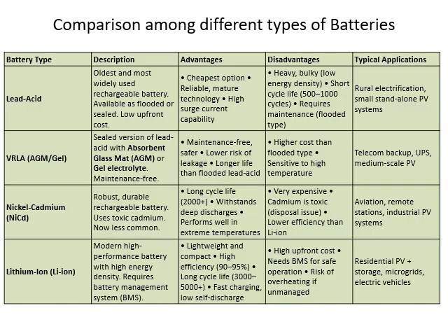Now we will talk about the different categories of these batteries, right? We are going to compare these four types. So we will first look into where we are going to apply this, right? Based on the application, we should try to see, then we will compare between them. So we can see that for typical application, rural electrification, small standalone PV system, it is suitable to go with lead acid because it is quite cheap, but it's heavier, right?